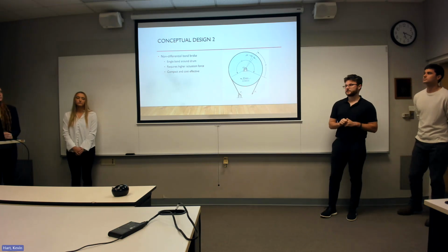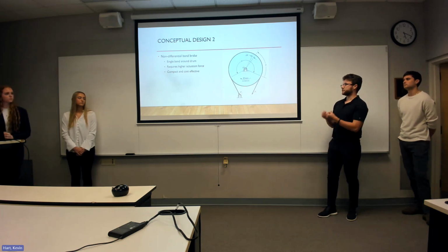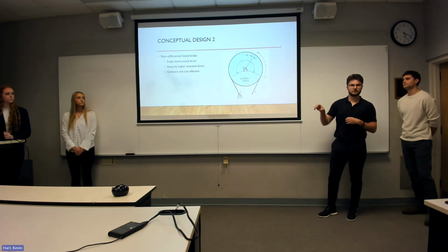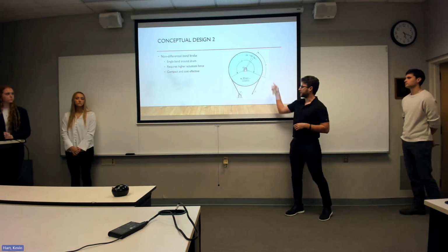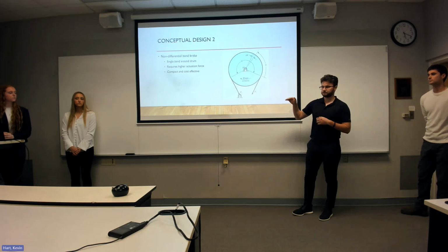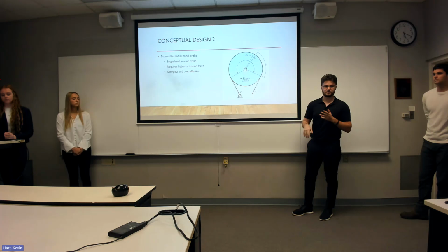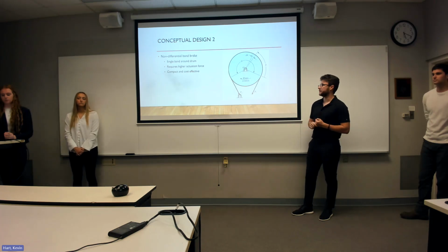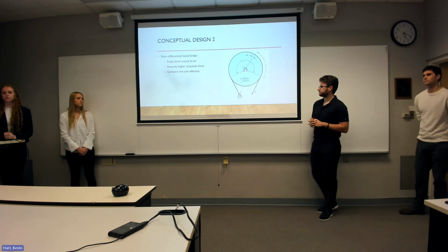So our next 3 designs are all different types of band brakes where essentially there's a drum that's pinned at the center that's free to rotate, and there's a band that wraps all the way around it and is connected to a lever arm, either above or below it, just depending on the design configuration. This is the simplest type. This is a non-differential band brake.